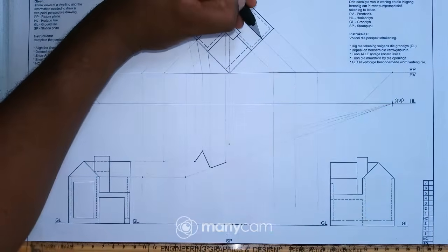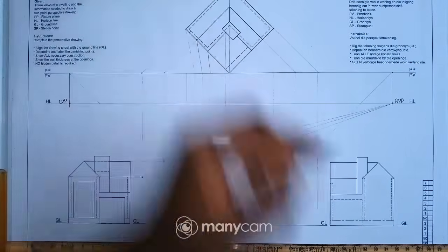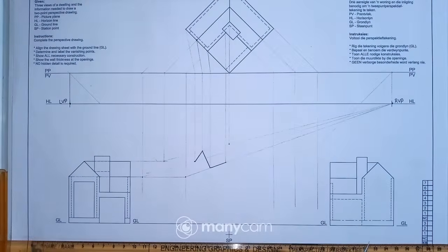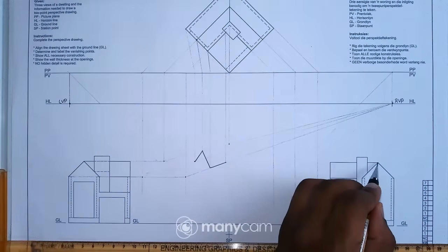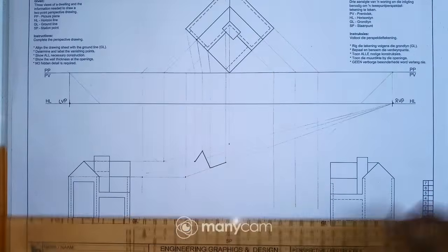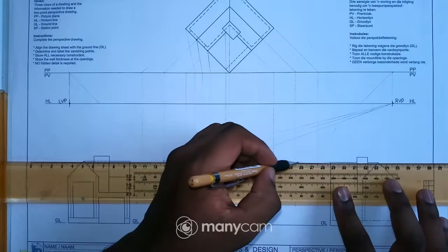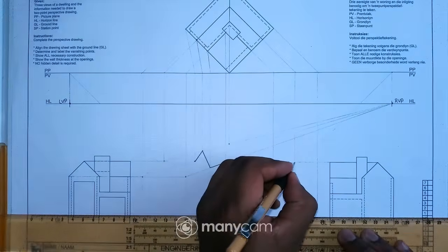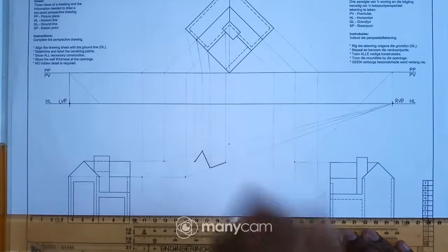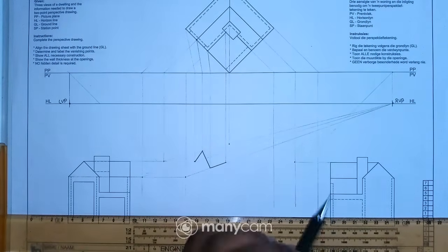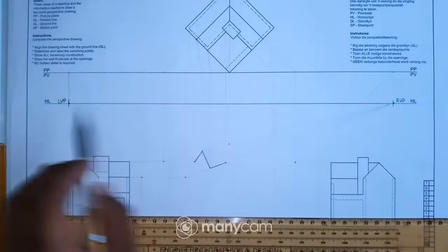Okay, so I'll start with this point. Where is this point from my right view? That point is right there. So this is the height of the roof, right? So I can just project this height of the roof to that line, that vertical line there. So I have a point. So this point I have to project or take this point to one of these 2 points.